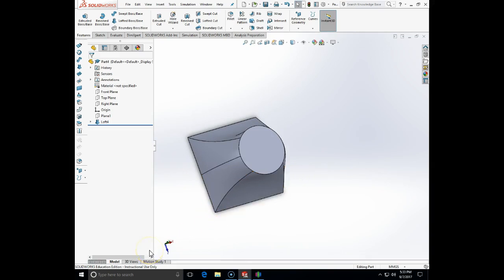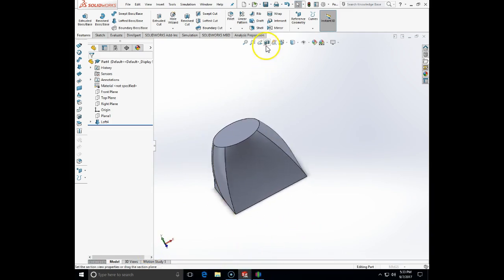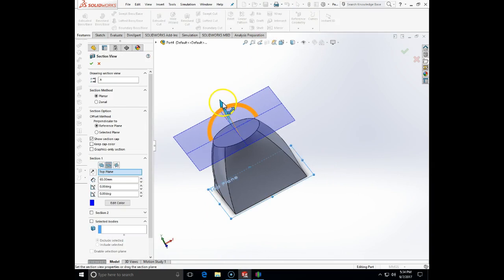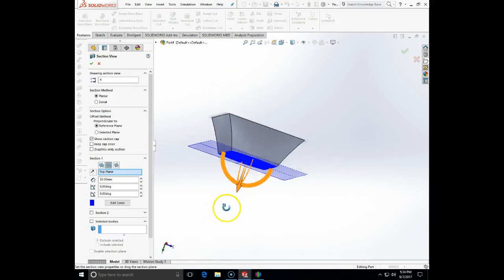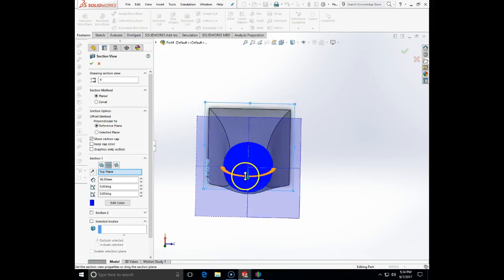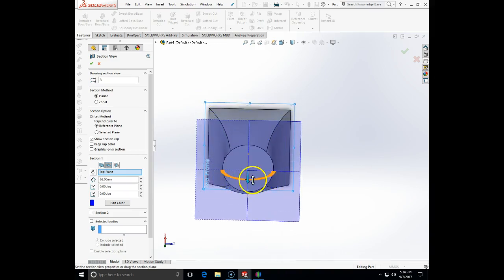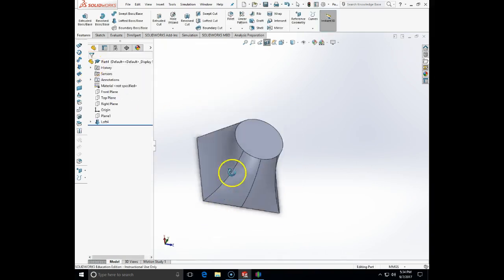So let's make those square and the circle, and let's make a loft, and then you can play with the arbitrary guide curves. And just to see what we have done here, look now at these transitions, how they actually look as we go from the square to a circle with the help of those guide curves. Look how the transition actually changed. Quite different than the initial loft.